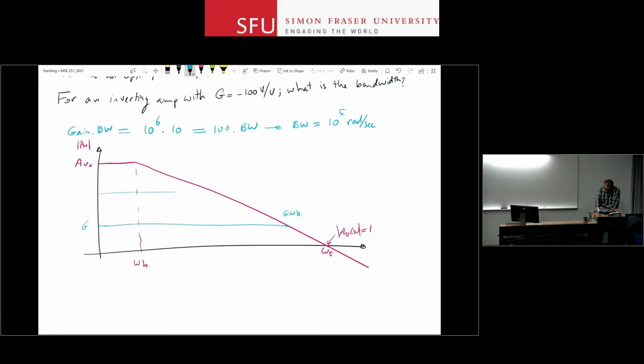And for different gains, it's going to be the same. So let's say G1, G2. It goes up to this and then starts to drop. Up to this and starts to drop. And they follow the same curve once they hit the 3 dB corner, right? But there is give and take, as usual. If you want more gain, you have to sacrifice bandwidth. If you want to have bandwidth, you have to give up some of the gain.